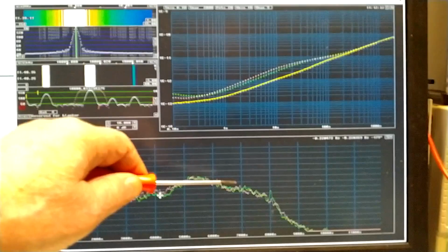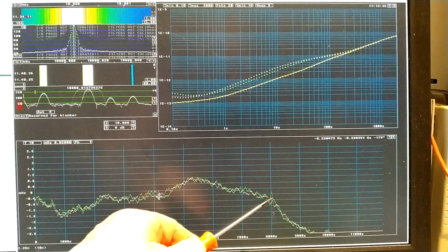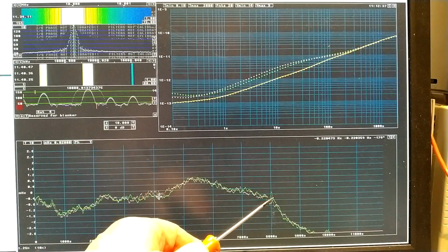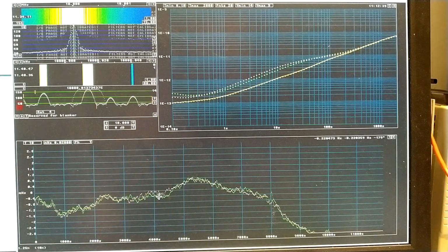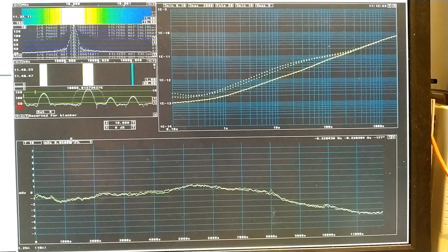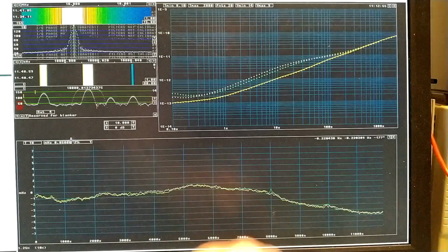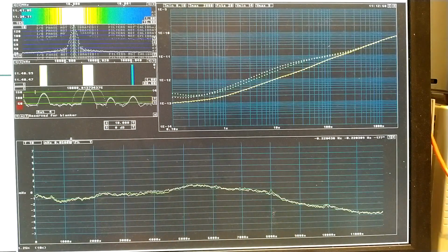And then there is the noise. Here is when I entered the room and removed the camera, and now I put it back. To see better, I will change the scale. And what these variations are, I cannot say for sure. Most probably it is my test oscillator that varies a little with temperature, or it could be related to the LPRO 101, but not very likely.